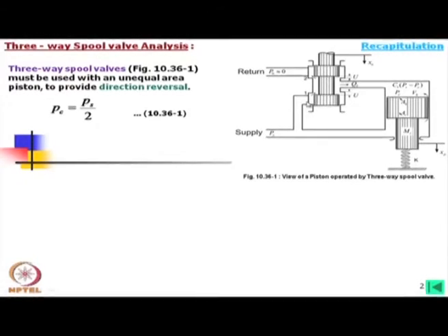This means that while we are opening this side, if we keep it closed, then supply pressure is going to this side, and this is being moved in the upward direction. Whereas, if this is opened, then oil is going through this, and this orifice is controlled in such a way that part of the oil will go to the control side, or in other words the head side of the piston, to control the motion of this piston, and part of the flow will go back to tank.